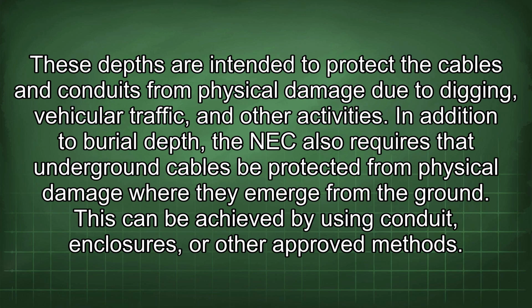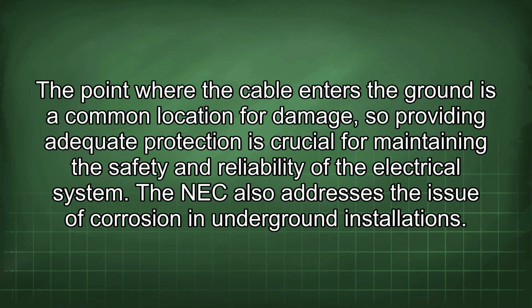In addition to burial depth, the NEC also requires that underground cables be protected from physical damage where they emerge from the ground. This can be achieved by using conduit, enclosures, or other approved methods. The point where the cable enters the ground is a common location for damage, so providing adequate protection is crucial for maintaining the safety and reliability of the electrical system.